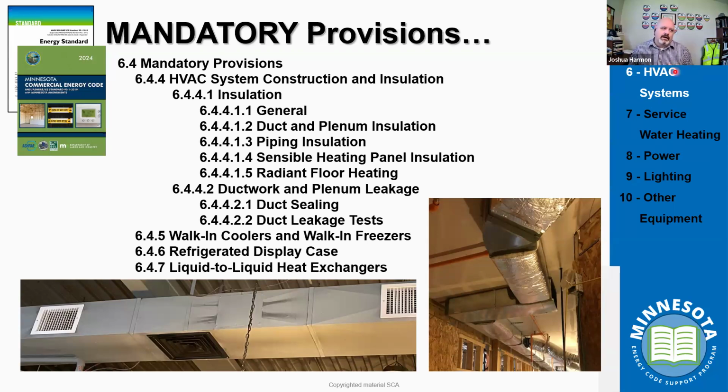Remember, when we insulate ducts, it's really less to change the temperature of the air as much as it is to maintain the temperature of the duct itself in relation to the air that travels through it. That's why you're not seeing huge values. That's why you're not seeing an R30 wrapping a duct. You're seeing an R6 or an R8, because really what we're looking at is maintaining the temperature of this heated duct more so than tempering or controlling through the duct itself the air that's already potentially thermally charged or cooled.